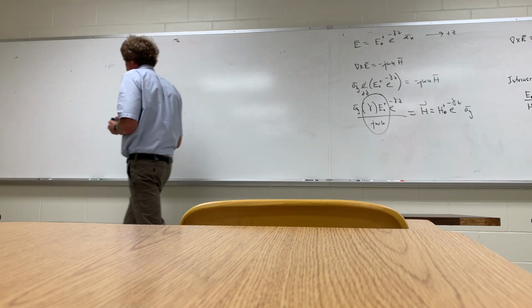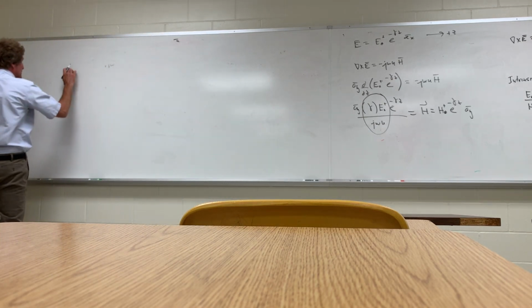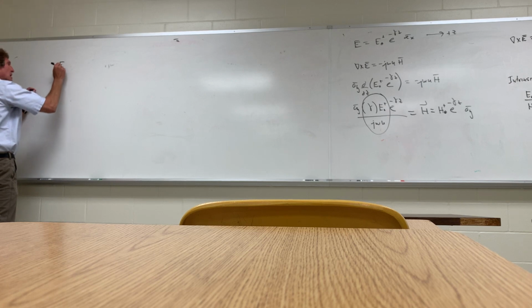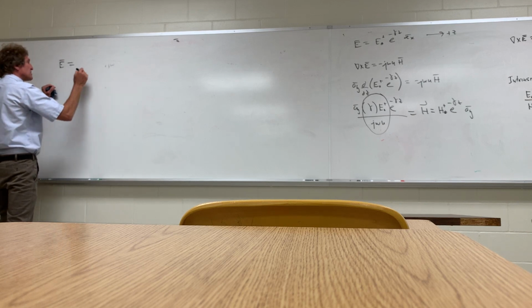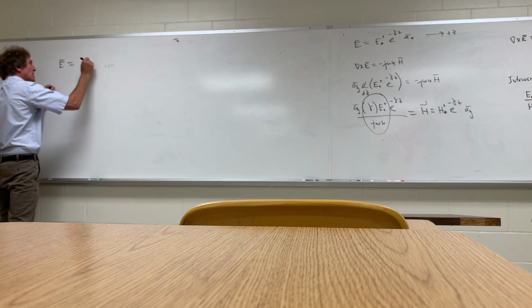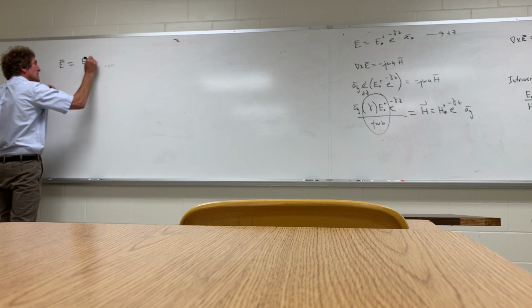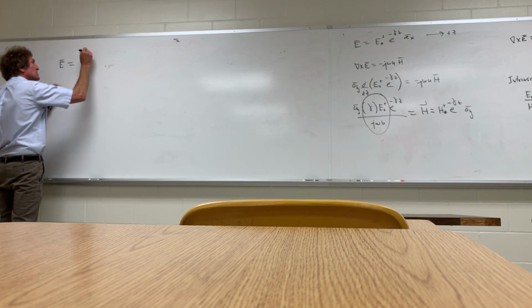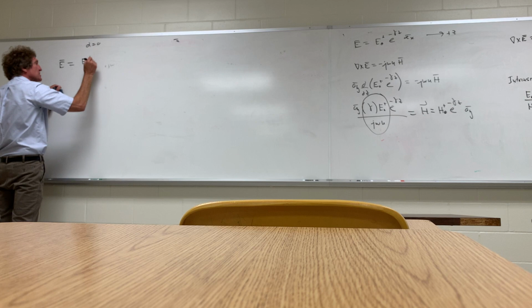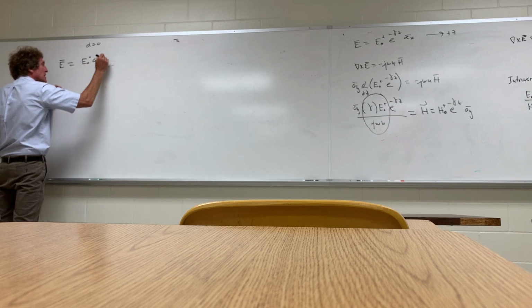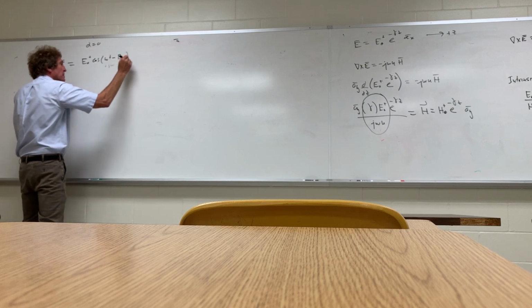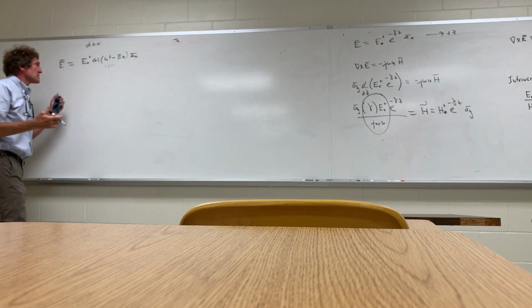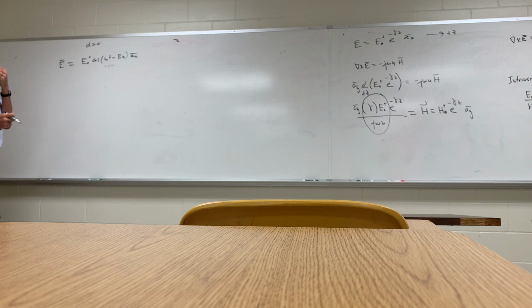Remember, I'm going to go to the time domain now. If I have an E field moving in the positive z direction, it will be some E naught plus times, and I'm going to assume alpha is 0 for this one, times cosine of omega t minus beta z, a_x. This would be a legitimate wave propagating in a lossless medium.